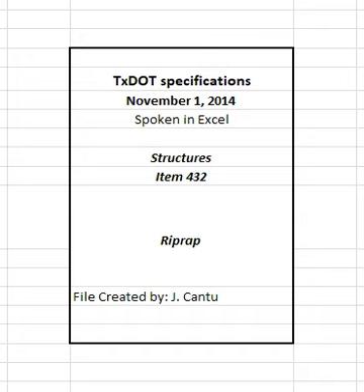Item 420, concrete substructures. Item 421, hydraulic cement concrete. Item 431, pneumatically placed concrete. Item 440, reinforcement for concrete, and DMS 6200, filter fabric. 2.1 Concrete riprap. Use Class B concrete unless otherwise shown on the plans.